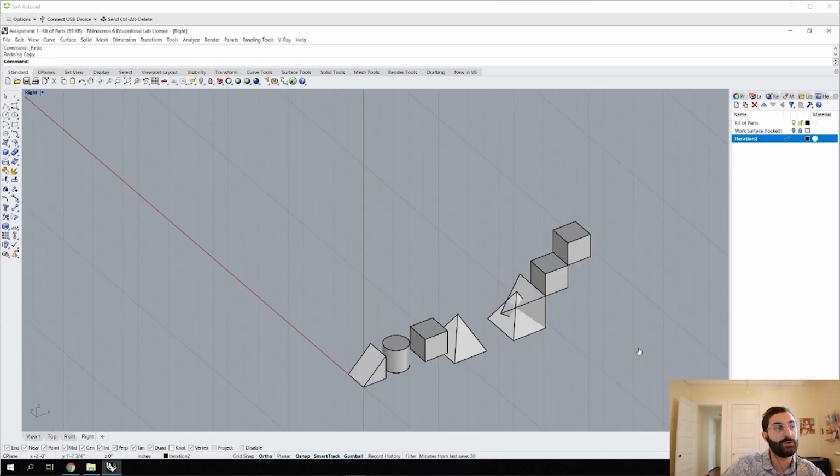If you click and drag, it creates this box here, and as you can see, if I go to the right, it's a solid box, and if I go to the left, it's a dashed box. So if I drag select, if I go through these, things that go running through the box will be selected. See that if I just click it just a little bit, it'll select it.